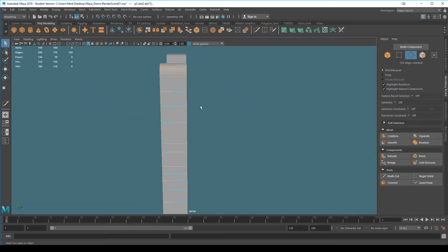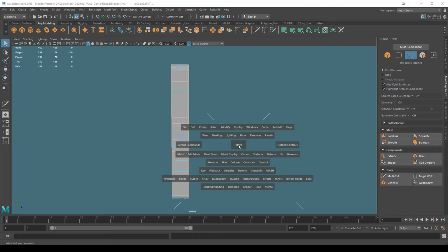Very easy to deselect those. Let's just come in here. I'm not even going to a proper orthographic view, I'll stay in the perspective view. Hold down Control, just Control, which gives me the minus symbol on the cursor, which shows me that it's going to deselect. Now moving my cursor into roughly the center, maybe I'll zoom in a little bit, and make a big drag selection through here, and it deselects all of that in one big hit.